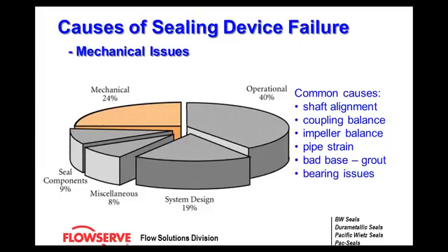A bad base is another form. Is it grouted properly? Do you have a soft foot? Are there any loose bolts? And of course, bearing issues. As the tolerance on the bearings wears out and opens up, you'll have shaft movement. Again, this leads to a mechanical seal failure.